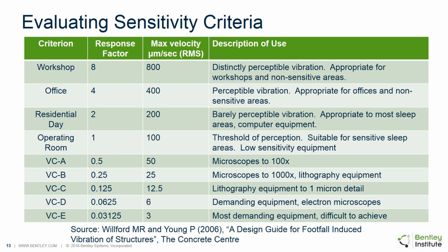So by calculating accelerations and velocities and then converting them into response factors, we can envelope for a floor the maximum response factor at any given location. We can create a plot of all of those and get a quick understanding in one single plot what the most susceptible locations are at any given floor. And we'll look at that in just a few minutes in an example.